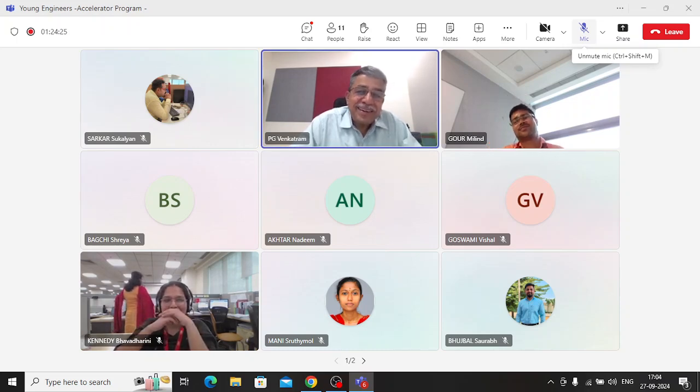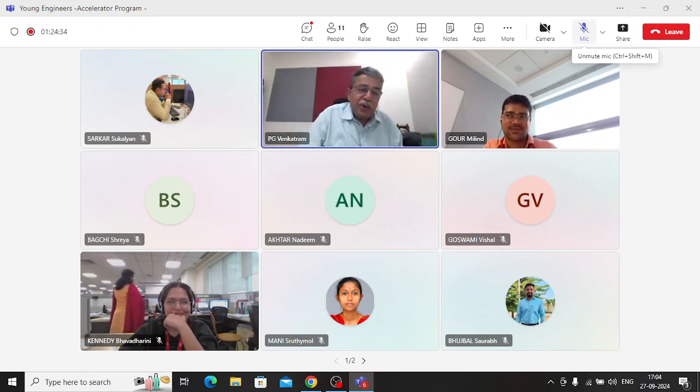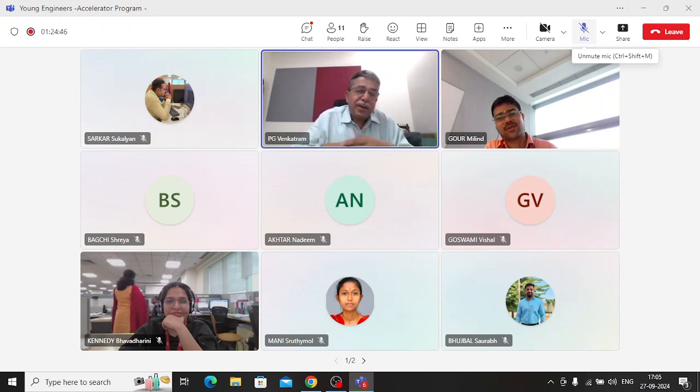Even if we transfer it, this is addressed to Shreya also. If you say I tie it, anchor it, and transfer the axial compression onto the deck, what do you think will be the buckling strength of a kilometer-long member, or even, including end to end with nothing at the pylon, about 2 kilometers long axially compressed member? Let's say I provide only bracing connection at the pylon for lateral restraint. So it's a 1 kilometer long axially compressed member.